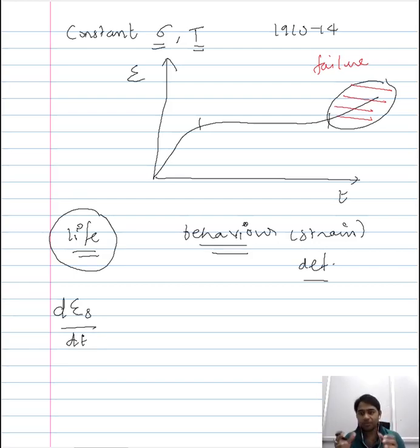So when you focus on the life of a material, then you are largely considering the steady state creep behavior of the material. And in the previous lecture, when we considered the transient creep of a material, we saw that when we focus on the deformation exhibited by a material in an application, we consider the strain of the material, the strain exhibited during the creep testing.